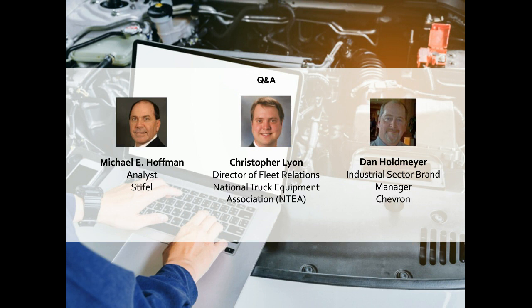I think the other side of maintenance that I see with the bigger public companies and the bigger privates is this idea of being much more vigilant about preventive maintenance. You have lower life cycle costs with a preventive maintenance program than you do with reactive maintenance. And I think the third item that is interesting is study and track the use of OEM versus aftermarket. I'm not saying that you should only use OEM. I'm not in that camp at all in that context. But study your data and figure out, did you really get a savings by using aftermarket parts